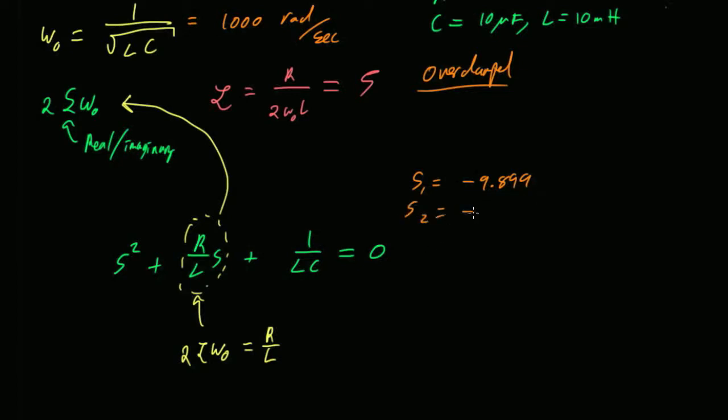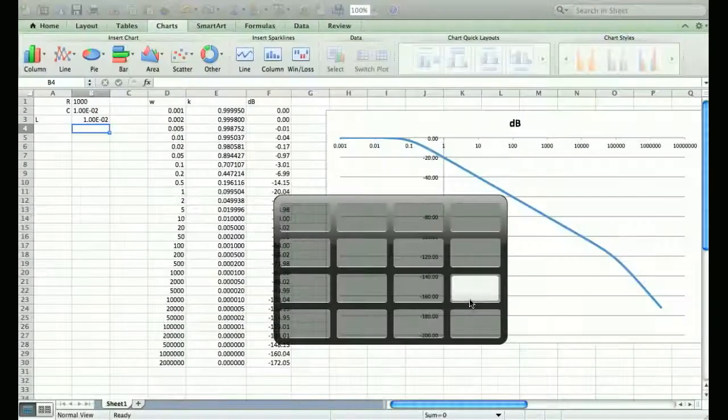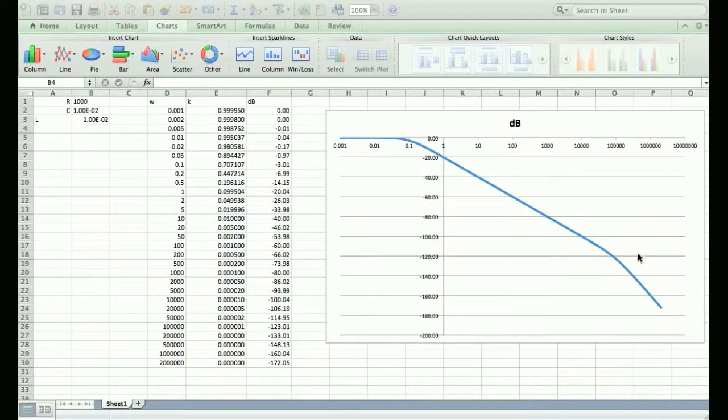Now, if you solve this characteristic equation for these two roots, do you remember seeing how the plot kind of kinked at those two points? See how it was linear during this portion and then dropped off and looked more like an RLC right there? The frequencies at the kinks end up being the roots of the characteristic equation. I know that sounds like magic, but I'm going to draw a plot here to make that more clear.